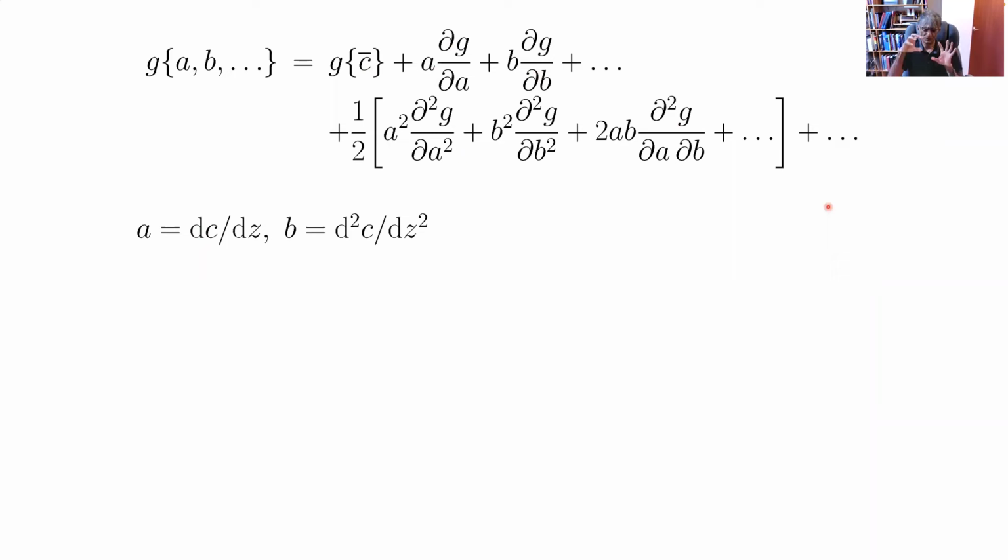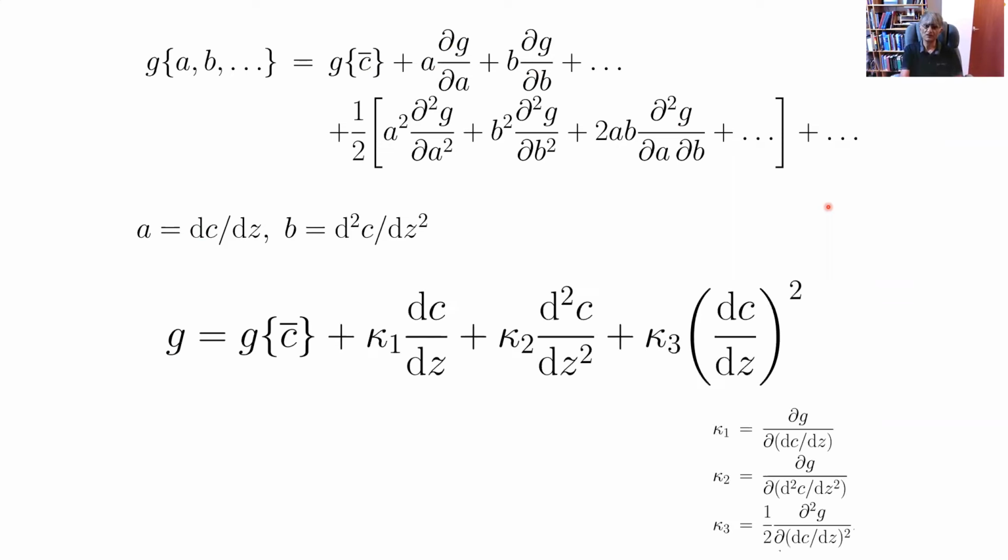So when we look at a heterogeneous solution, the average free energy that you would get if the solution was homogeneous is different from that for a heterogeneous solution. So if I substitute for A and B in these terms and do a lot of algebra, then you end up with an equation like this, where this is assuming that the solution is completely homogeneous. This is a term which depends on the gradient, on the second derivative of the gradient, and on the square of the gradient.